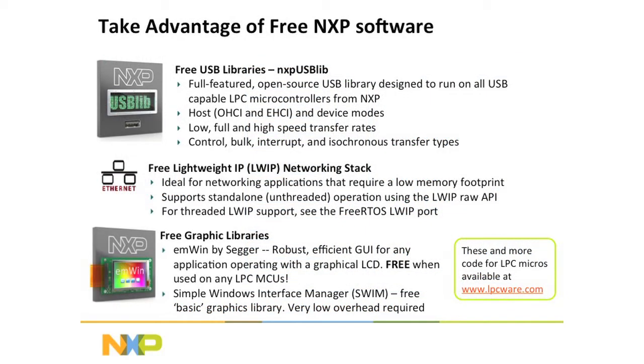All right, I want to give you an overview of some of the software packages that we have available at LPCware for NXP parts. One of the main ones is the USB library, NXP USB Lib, which is a free, open-source, full-featured USB library designed to run on all capable LPC microcontrollers.